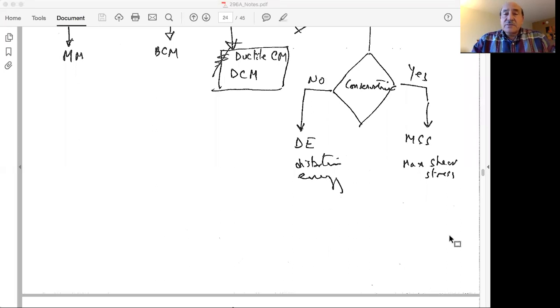So we're going to start and do a share. If we discuss Castigliano's theorem, its importance is that we can immediately determine deflection at any given point without having to deal with integrations of the equations that go from the load to the shear force diagram to the bending moment diagram to the deflection. So we didn't have to do all of that, and we have a direct way to compute the deflections.